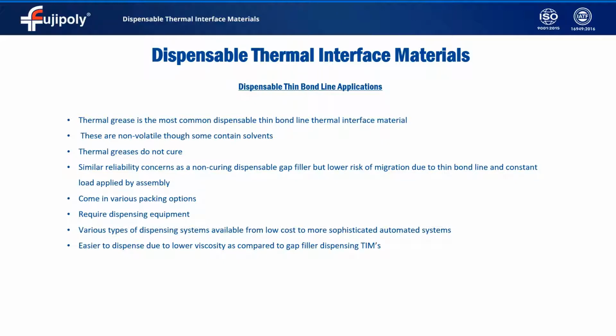Now, some manufacturers and engineers dislike using thermal grease, and so there are solid alternatives like thin film silicones, thin gap fillers, and phase change, but it's difficult to get the same performance of the grease, especially if your bond line is under 100 microns. So the greases definitely still have their place in the industry.